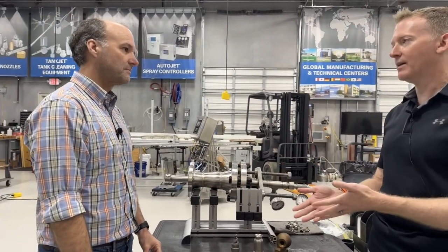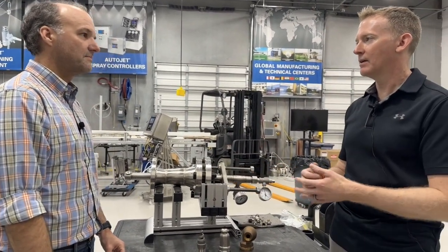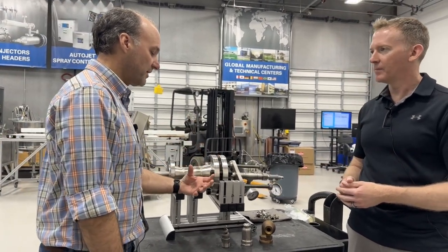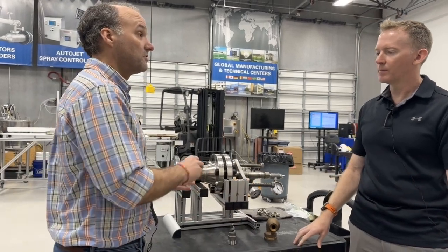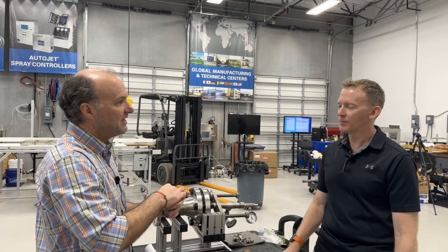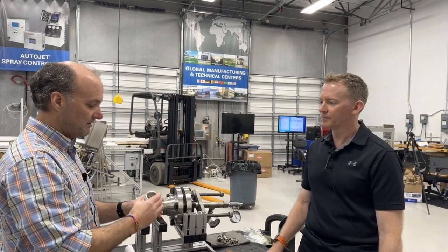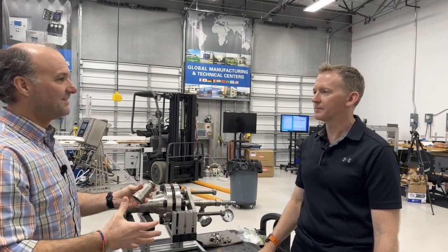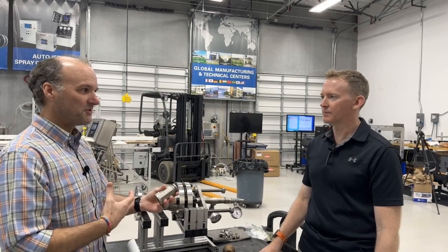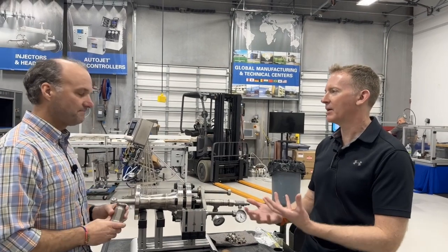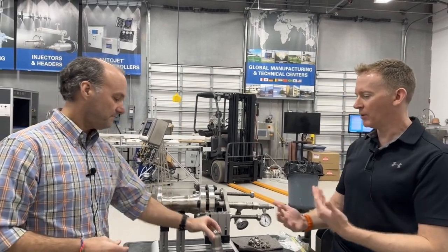But yet with that, we still see fouling. Right. And I think it sometimes comes with, if you have particles or matter that is able to flow through your strainer, it could build up over time inside the spray nozzle. And the only way around that is to use a bigger spray nozzle or a larger free passage. But then you're dealing with flow versus pressure scenarios that you have to understand. And you change the droplet size, you change the dynamics of the entire system. So there's really pros and cons to be said.